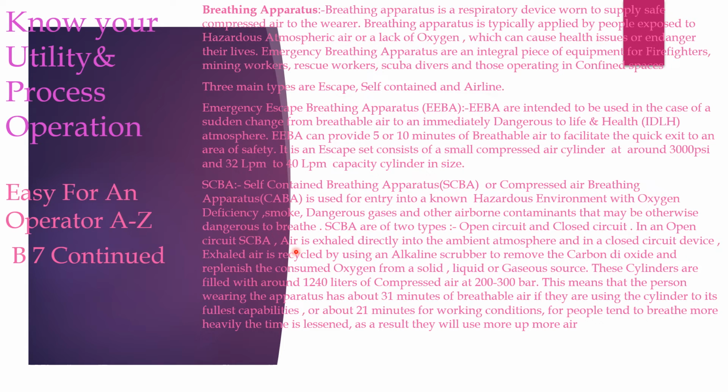In an open circuit SCBA, air is exhaled directly into the ambient atmosphere, and in a closed circuit device, exhaled air is recycled by using an alkaline scrubber to remove the carbon dioxide, and the consumed oxygen is replenished from a solid, liquid, or gaseous source.